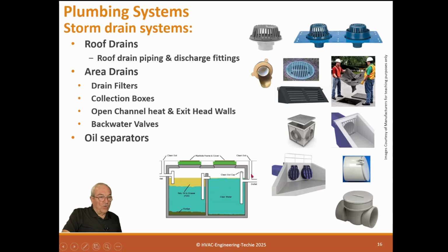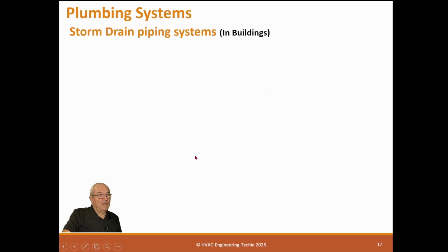And here again is oil separators. So this is the same thing with a sewer. The storm comes in, it precipitates over to the other side through this pipe, and this oil is able to be pumped out when it rises. And this is to prevent, if you have water that's collected from an area where trucks and vehicles are, you'll have to put an oil trap in before you can release it into a waterway. That's just to protect the waterway.